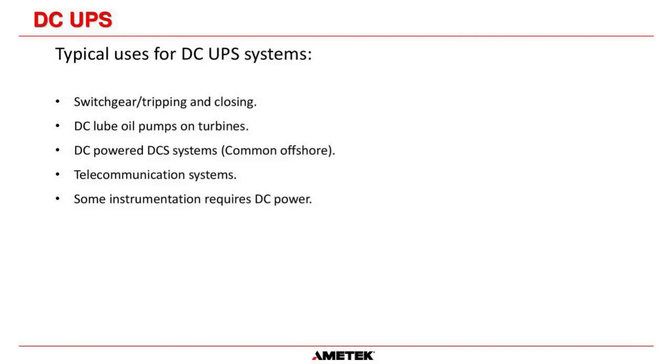Okay, and it's very, very important that those tripping and closing springs can be charged and discharged, and the switchgear can disconnect power when there is a power outage, because if there is a fault when all AC power has been lost, those batteries are critical to allow that fault to be cleared and not cause a fire on your MCC.